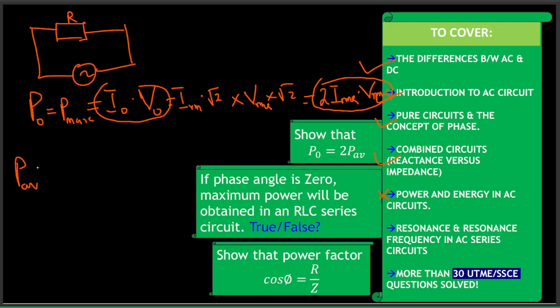Now, when you come to average power, some people call it true power. You can as well call it the active power, and wattage. Now, this is not to take us to the power triangle, even though this is above your scope. Using the power triangle, we have the active power here, we have the reactive, and then we have the apparent power.